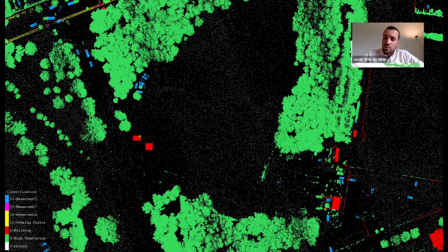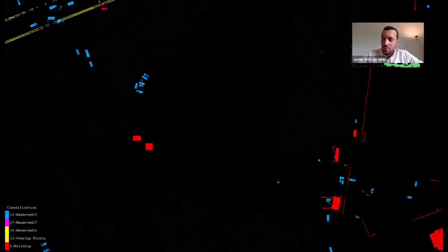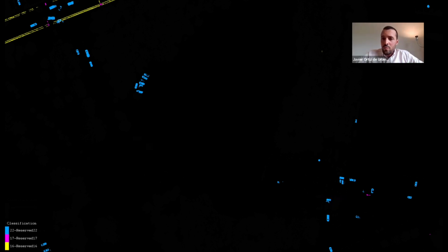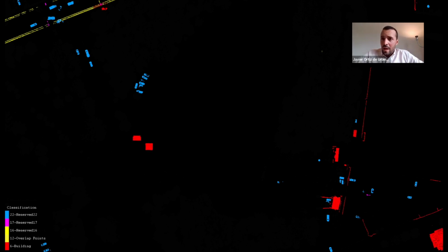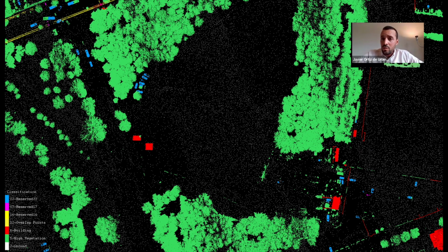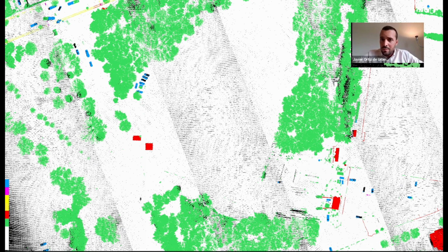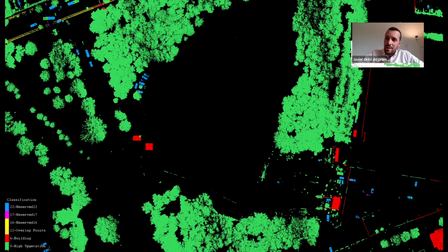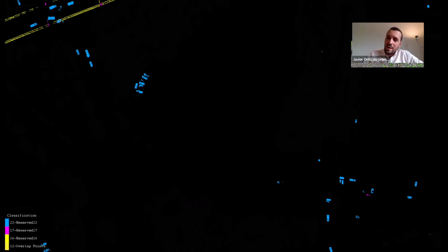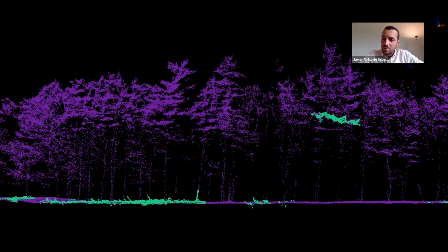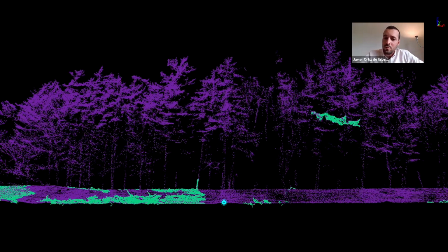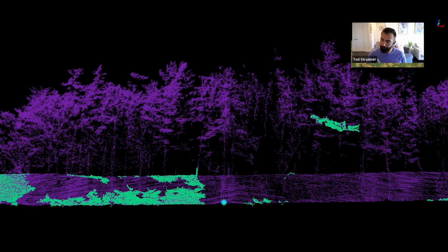It really depends on what the data is going to be used for. For example, we see a lot of usage of photogrammetry for cadastral applications. So to map a city for a cadastral map, you don't even need a very high resolution. And that can be achieved with an orthomosaic model. Also, 3D models captured with an oblique camera are very useful to that, not only to see the orthomosaic, but also the 3D shapes of the buildings, how many stories do they have, and so forth.